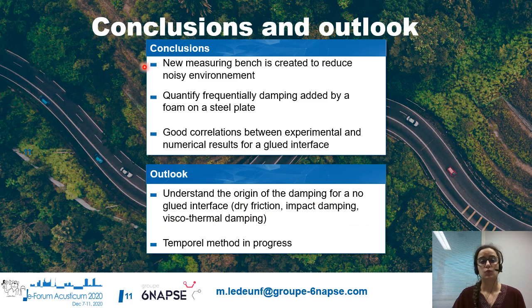In conclusion, we have created a measuring bench that reduces the influence of the noise at the boundaries, and a protocol to quantify in frequency the structural parameters of a bilayer structure with different contact at the interface. Preliminary numerical results seem to indicate that the damping induced by a glued interface is due to the viscoelastic effects of the foam.